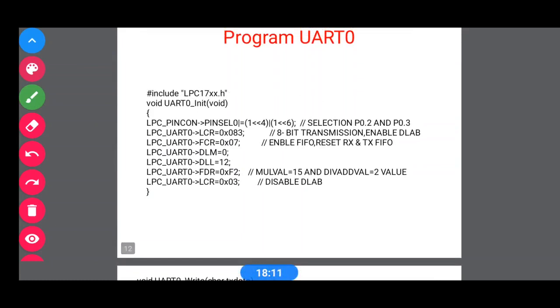In the UART initialization, the first thing we are doing is selecting pin 0.2 and 0.3 for UART0, which are the TXD and RXD pins.